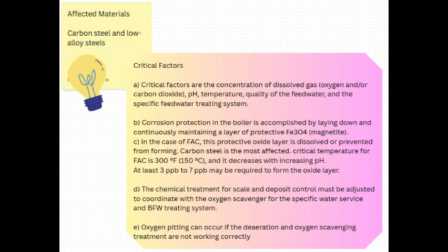Where else do these attacks happen? Is it just pipes? No, unfortunately, it's pretty systemic. You see it in the deaerator itself. The thing designed to remove the gases. Ironically, yes. And then downstream, feed water lines, heaters, economizers, the boiler tubes themselves, and all that condensate piping we just talked about. And it can be very localized sometimes, like right at the water line, the interface between water and vapor in something like a vertical reboiler. That's where gases can concentrate.